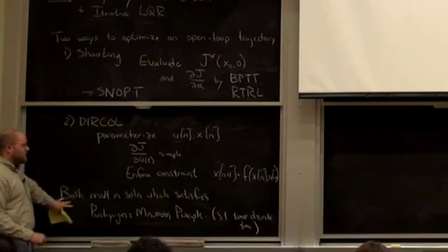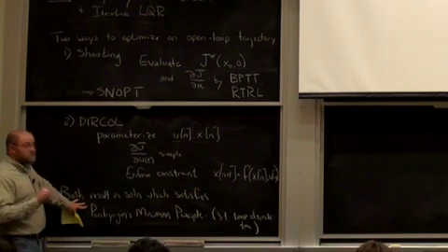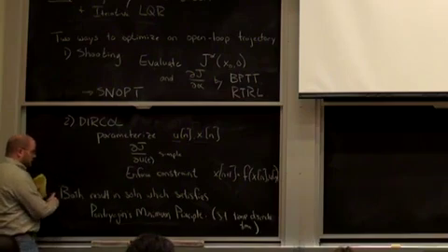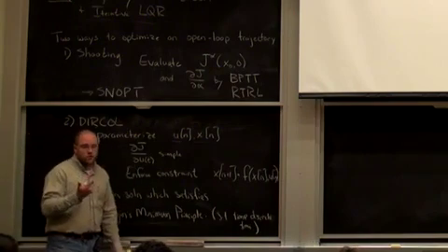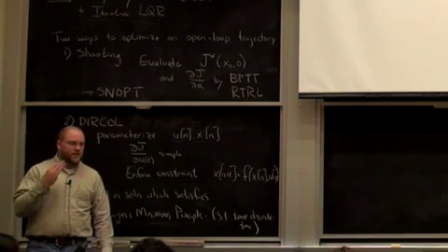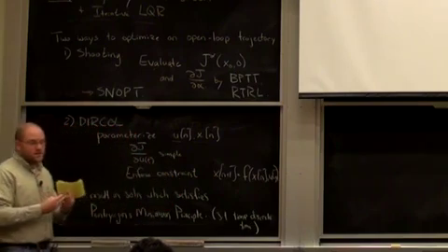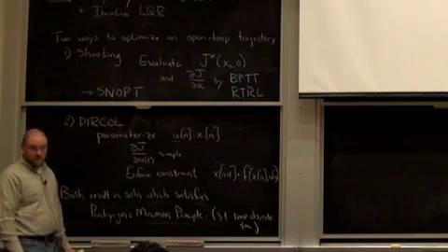I would only make this statement in the case where the controller specifically is the open loop tape, right? Because if I parameterize my trajectory by some feedback controller, for instance, then that's going to restrict the policy class. That's going to restrict the class of tapes that I can look over, which makes it a more compact, more efficient way to solve your optimization, but potentially prevents you from achieving a perfect minima.